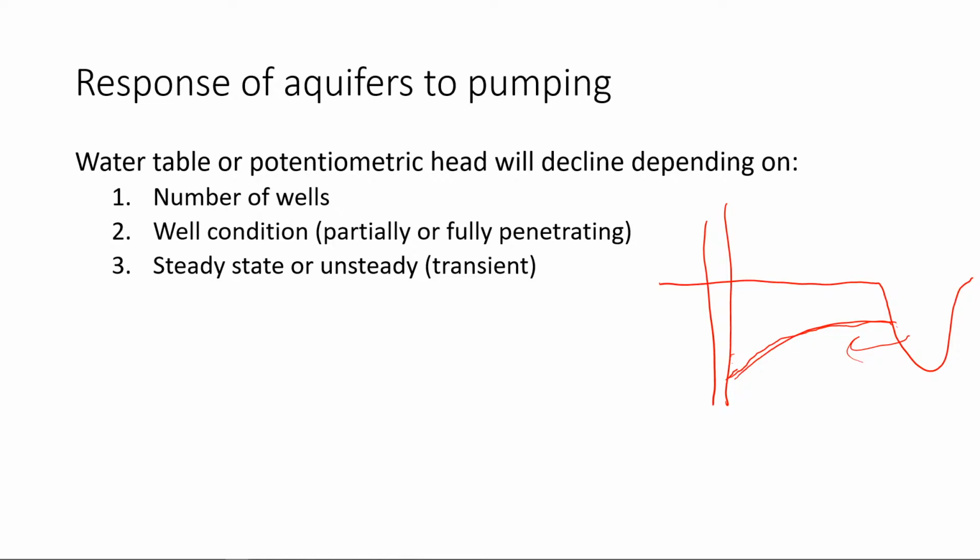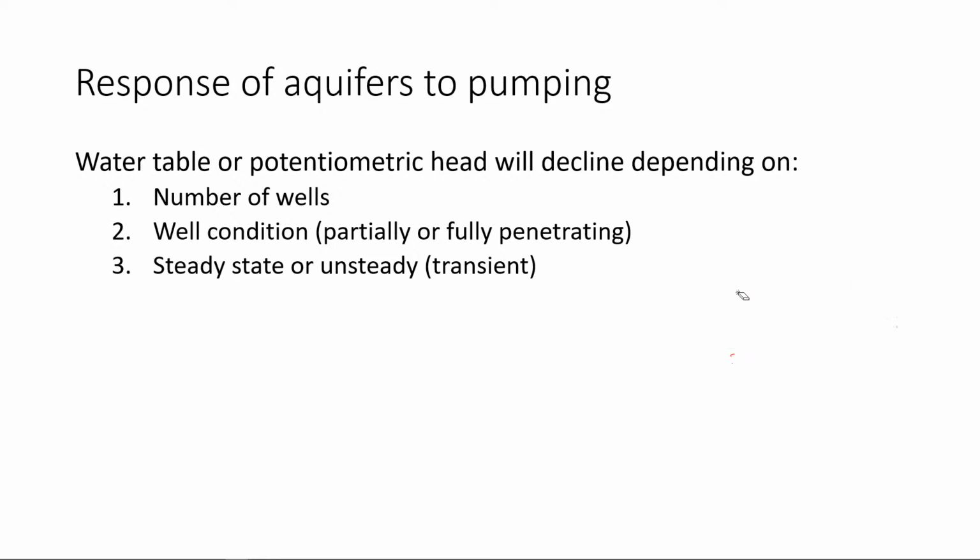That could be surface water, or spring discharge, so you'll find the spring discharge is becoming less, or submarine groundwater discharge is becoming less, or the water level at your river is falling down. This is called groundwater capture. But anyway, that would be an example where you reach steady state, where your drawdown is constant, it's no longer changing. That's called steady state.